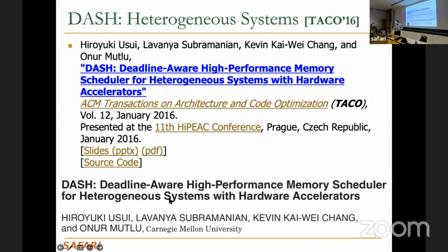And this is one of our latest papers that looks at CPUs, GPUs, and other hardware accelerators like audio and video accelerators. That is interesting. So if you're interested in this area, there are a lot of heuristic-based policies, and this is one of the most sophisticated heuristic-based policies. And people employ this sort of thing in real SOCs today. Real SOC memory controllers need to take into account all of these things.